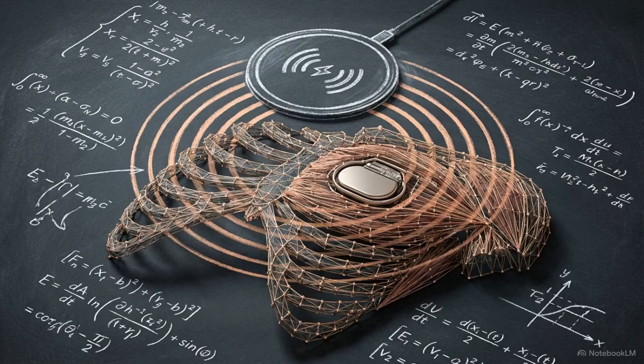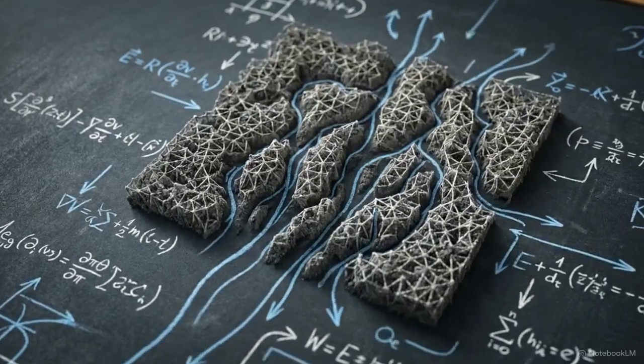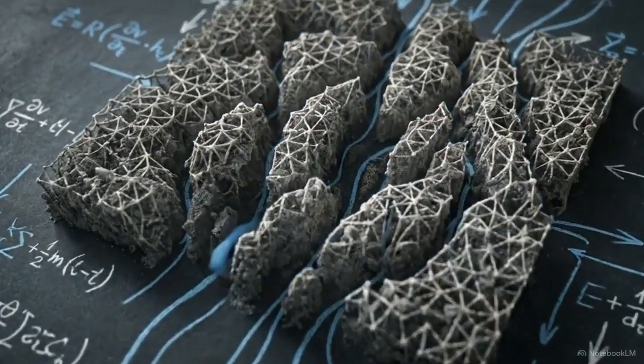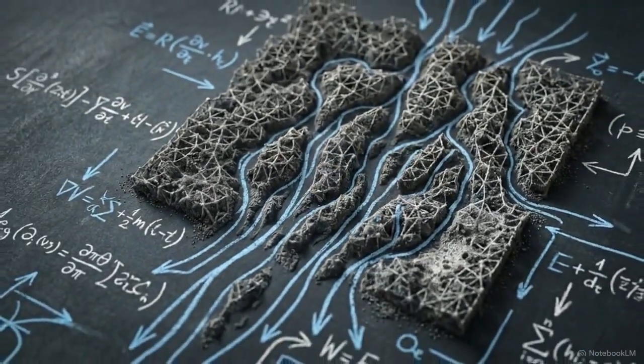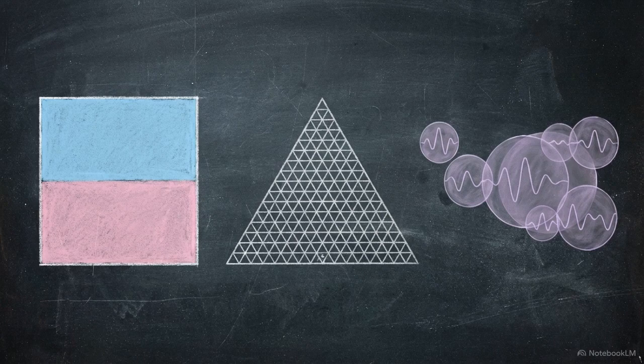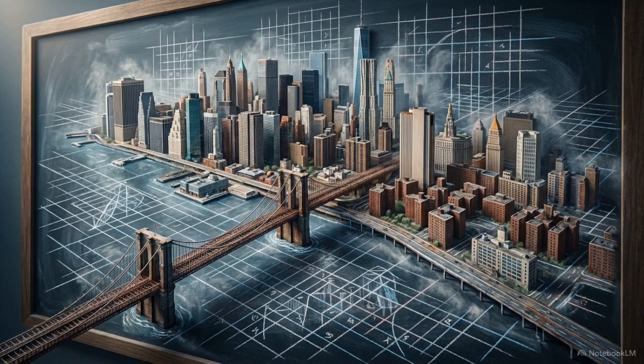This coupled architecture is also used for biomedical implants. It simulates how electromagnetic fields from wireless chargers generate thermal loads in human tissue. It also applies to poroelastic materials, where we model how fluids move through and deform porous solid structures, like Arctic soils or biological membranes. By moving beyond the limitations of standard Lagrange elements into mixed, adaptive, and meshless regimes, finite element analysis provides a unified mathematical framework for simulating the coupled, nonlinear interactions seen in real-world engineering.